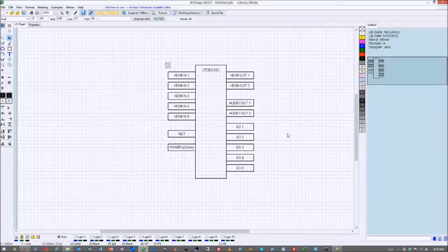So now it's a complete drawing, and I can use it. But what we also need to do is to add some snap-in points. So in this case, I'm going to go ahead and add a snap-in point right into here. Okay. And right on the left-hand side, there's a tool called snap-in point. So let's go ahead and take this tool, and we're going to put the snap point right here in the middle. All right. And I accidentally inserted a second one.